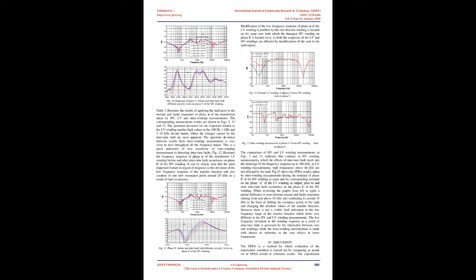The measurements performed prove that the voltage gain transfer function, when measuring across a HV winding with other windings floating and not shorted, is more sensitive to inter-turn winding faults. In addition, the deviation of the low-frequency response of the LV winding located on the same phase of the damaged HV winding is large enough to indicate the fault occurrence.